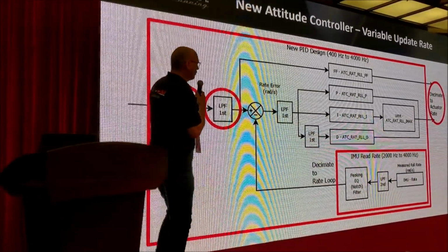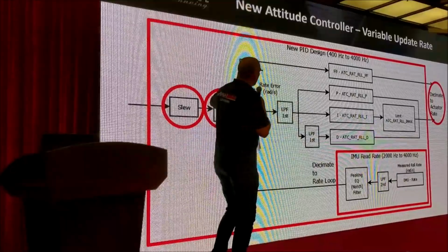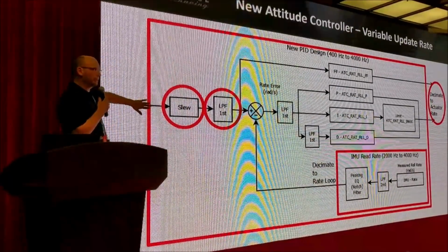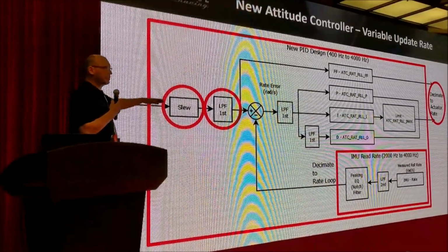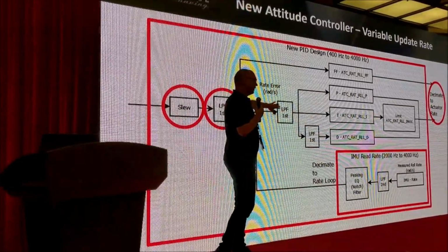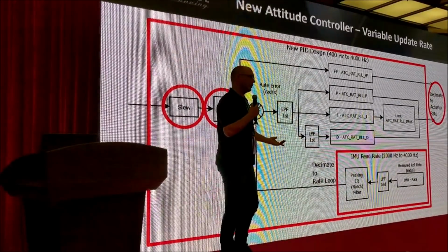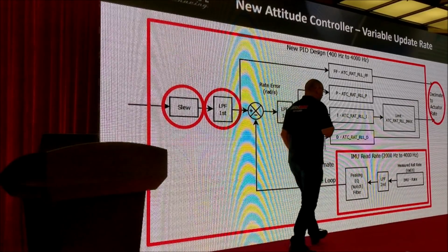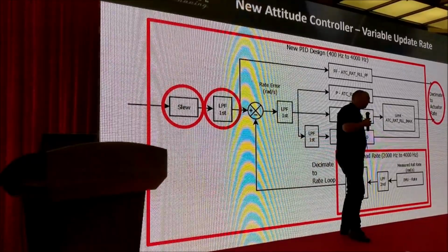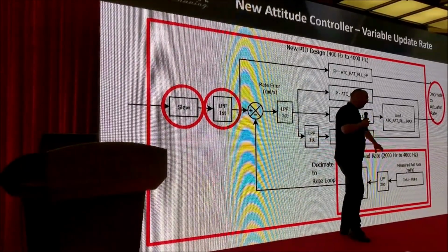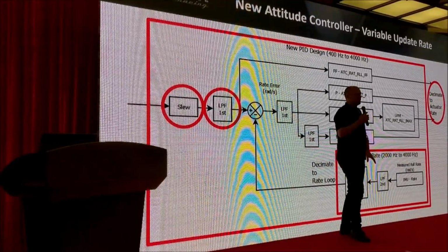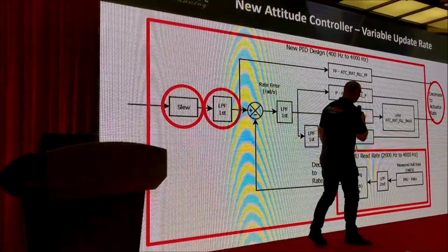Finally is the update rate. We want to be able to separate the speed at which we input these commands to, say, 50 Hertz, while running this inner filter, the PID loop, at 8 kilohertz. But in order to maximize the effectiveness of these filters here, we may want to run our reads at 30 kilohertz to provide the maximum noise rejection of our system.